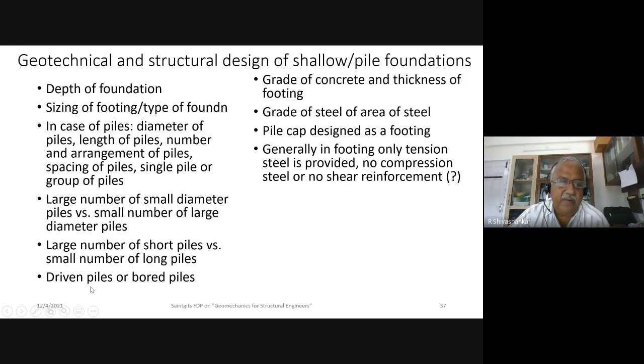Usually, the driven pile capacity is increased after installing piles, because you are forcing the pile into the ground. The soil around and beneath is compacted. But in the case of bored piles, you are making a hole in the ground, which means that you are releasing the overburden stress.